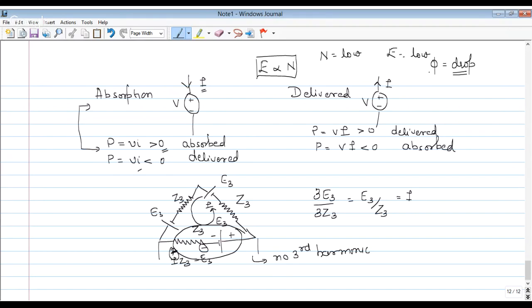And we see if flux drops, there will be a no load release, in which it will release the handle and bring the motor to a stop. That is, the 3-point starter is designed in such a way that if the magnetism or flux goes below a certain point, it has to turn off the motor. So the motor will stop at low speed. It cannot run at very low speed. Okay. That is one of the reasons why we can't use wide range of speed control.